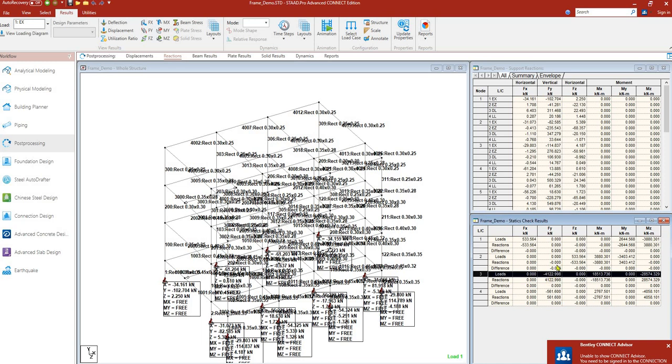Okay? So, ayan siya. So, remember that load case 1, ito yung seismic. Tapos, load case 2 is also seismic. And then, load case 3, yan na yung dead load. 4 is the live load. So, ito tayo sa 3. And then, reaction is vertical. So, kunin natin yung FY, which is ito.